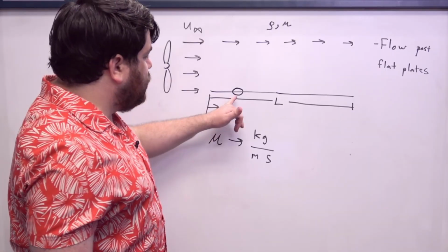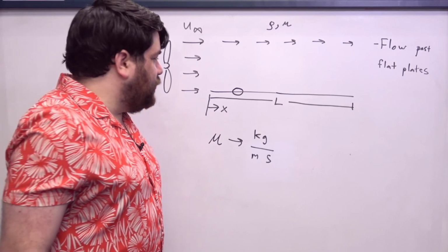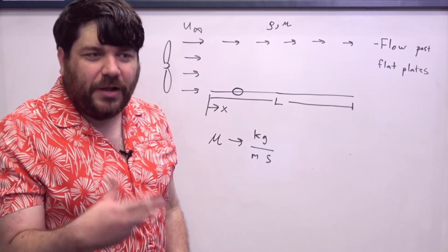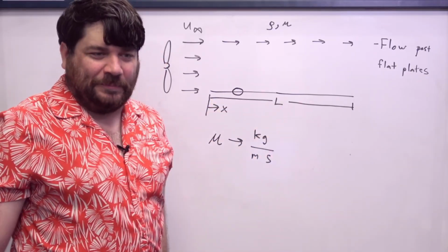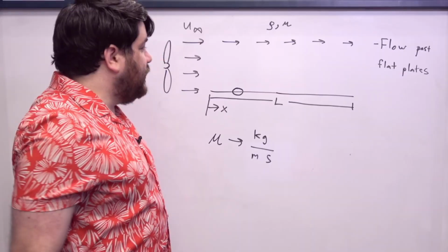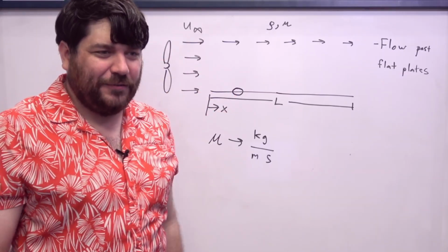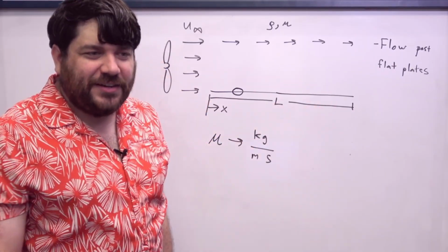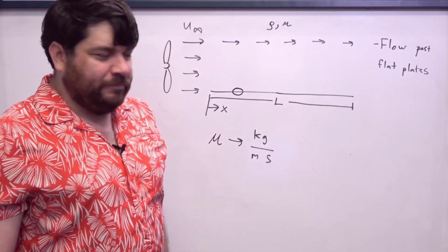If I try to make a measurement that's close enough to the surface, then of course I should expect that that average is going to include a bunch of molecules and particles that belong to the solid surface that are not moving. And so as a result, we expect that the flow speed, the thing that we call the flow speed of a liquid, drops to the speed of the object that it's in contact with as we get closer and closer to the object.